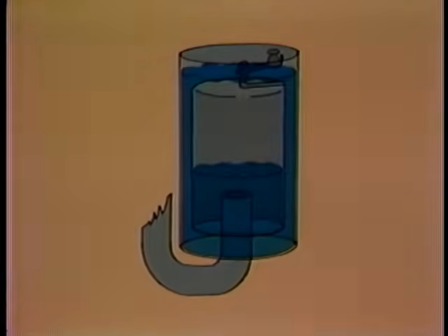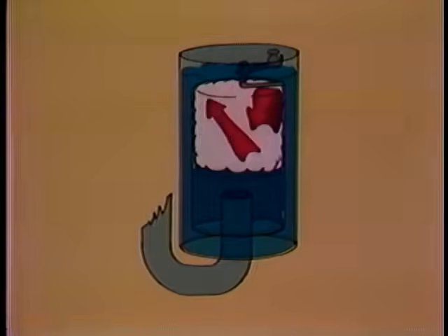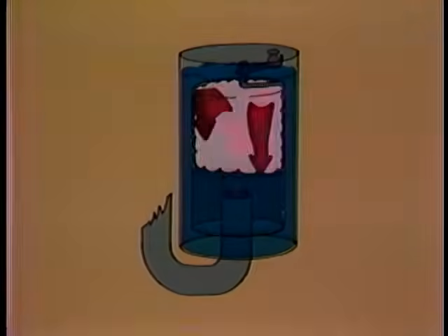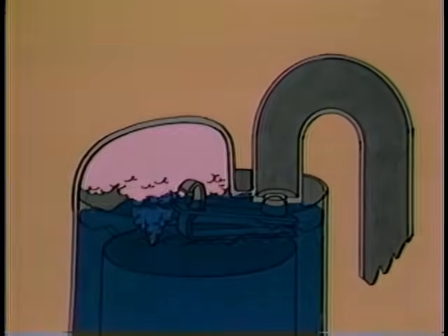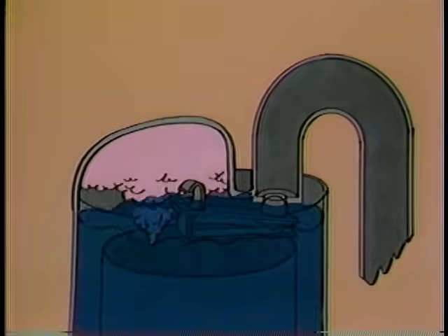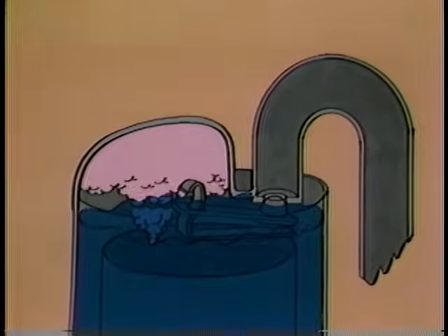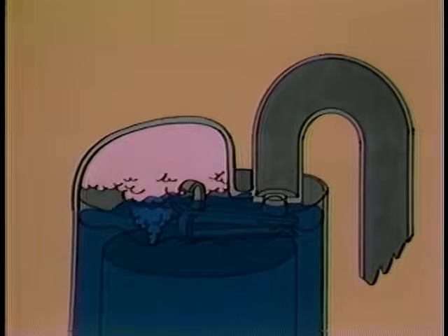This condensate provides a constant water seal above and around the bucket, preventing live steam from escaping from under the bucket. Finally, in the cap of the body is a space above the water seal where any non-condensable gases which have passed through the bucket vent will collect while the valve is closed.